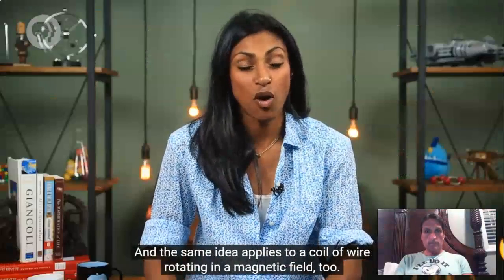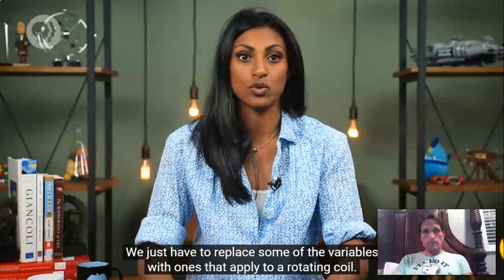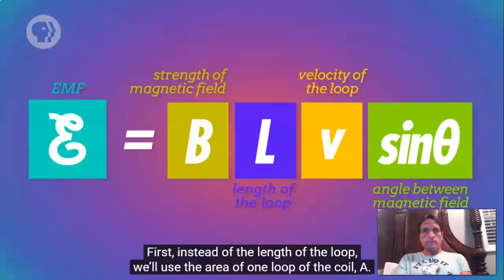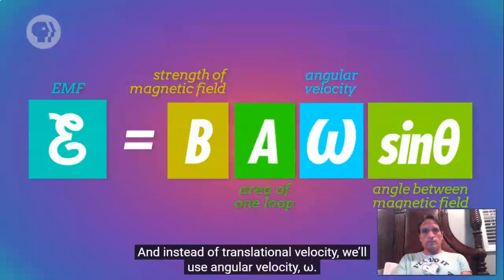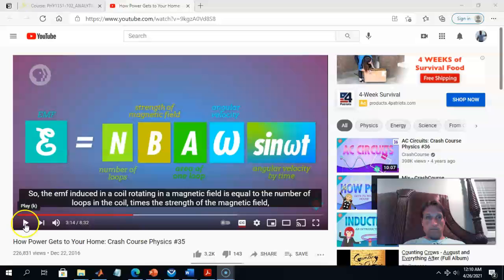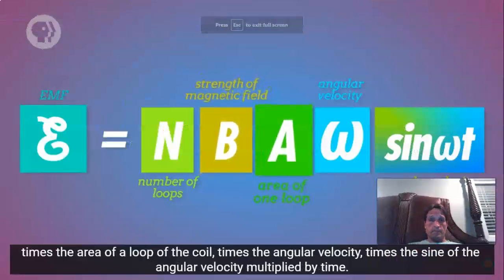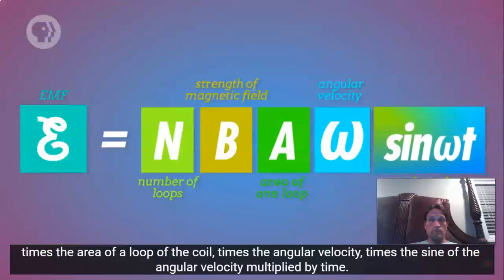And the same idea applies to a coil of wire rotating in a magnetic field too. We just have to replace some of the variables with ones that apply to a rotating coil. First, instead of the length of the loop, we'll use the area of one loop of the coil, A. And instead of translational velocity, we'll use angular velocity, omega. Next, the angle theta is just equal to the angular velocity times time. So the EMF is equal to the number of loops in the coil times the strength of the magnetic field times the area of a loop of the coil times the angular velocity times the sine of the angular velocity multiplied by time.